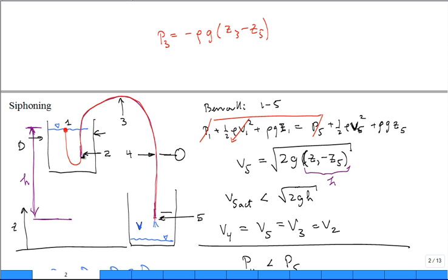So this is very, very interesting. This is a stationary water tank. I come over here to the side, very far away from the tube. I come down, I look at the pressure at this elevation in the tank, over here to the side, far away from the tube. What's the pressure there? Rho g h. Is it in a state of vacuum? No, it's a hydrostatic head. There's heavy water on top of it, right? It's got positive gauge pressure.